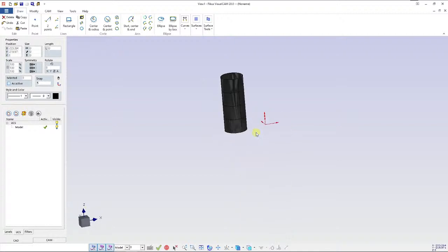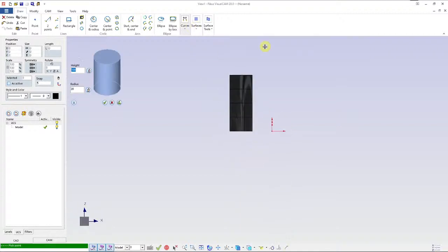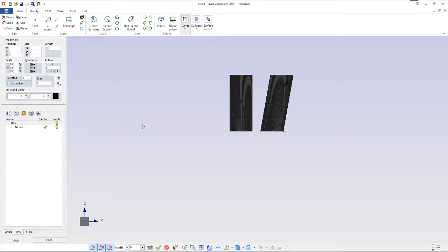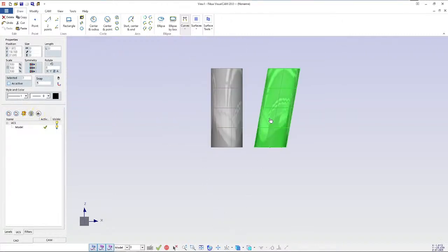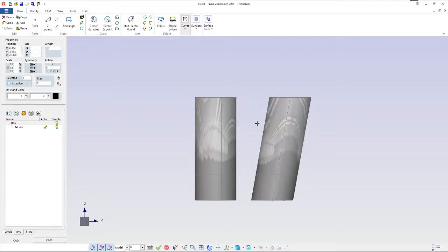So similarly, this is in the front view. Now, if I want to have a tilt in the cylinder, I have an additional tilt angle which I can give over here. And when I click it, I can see that there is a tilt in the angle. So this way I can create the surface cylinder also with the tilt angle.